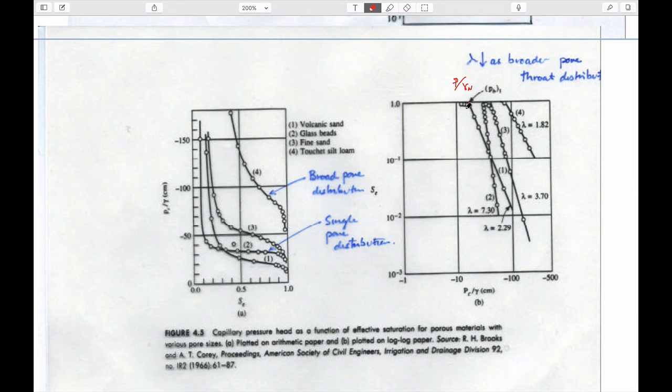The lowest bubbling pressure is going to be the one that has the lowest air entry, which is going to be this one. The one that has the steepest gradient on it, that is closest to parallel with this line here, is the one that once you apply enough pressure to push a bubble of air into the system, it's going to saturate all the other parts of the porous medium, so it's going to be very flat. So I'd guess that this one would be this one. Number 2 is this one, right? The most steep one here has to be this one here.